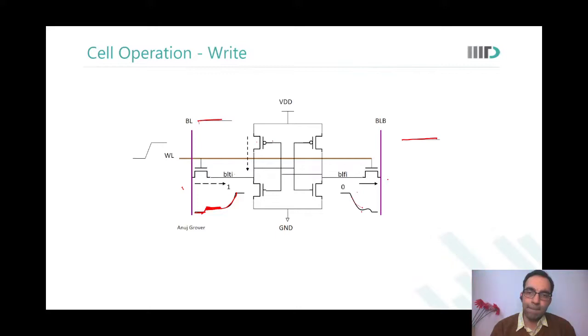The other bit line is in the read state, so this one we will keep precharged. Because we know this is a write cycle, what we could do is have a PMOS connected here, which is on during the write cycle. So this would remain at 1. This would not discharge. We may do that, we may not. As a designer, I have to decide if it helps me or not.